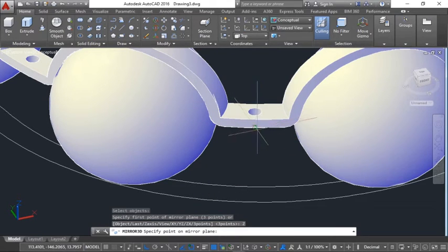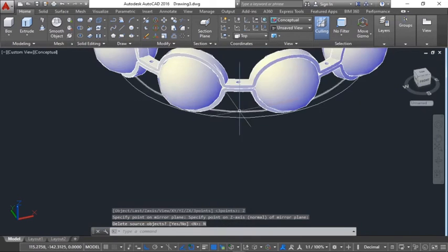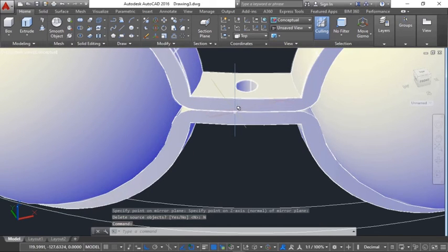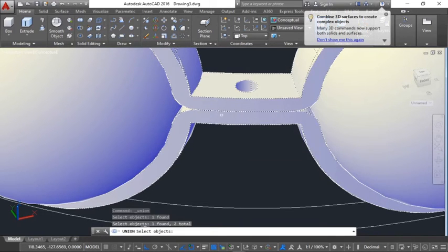At this time you're moving downward because I want to mirror down to fix that. Okay, so now you're having it correctly, because initially I wanted it to be like this, but it seems it was intersecting, right? So mirror union, select that and that to union them together.